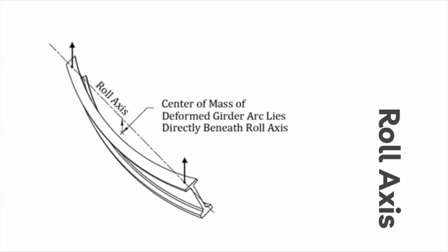If a girder is hanging, the roll axis connects the two points where the girder is connected to the lifting cables. If lifting loops are used, the roll axis is taken as the top of the girder. For rigid lifting devices, it is taken as the point where the device is connected to the lifting cables. For a seated girder, the roll axis connects the top surface of the bearing pad or support on which the girder sits.